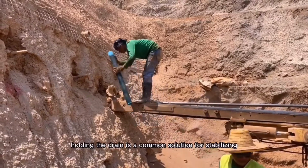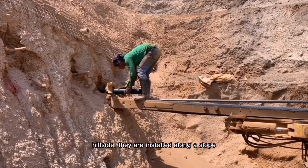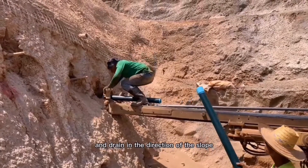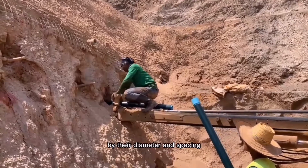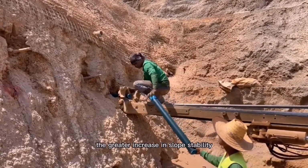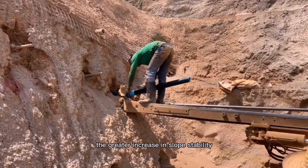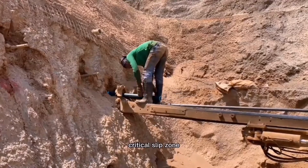Horizontal drains are a common solution for stabilizing hillsides. They are installed along a slope and drain in the direction of the slope. The effectiveness of drains is governed by their diameter and spacing. The larger the diameter or the lower the spacing, the greater the increase in slope stability, as well as their location in relation to a potential critical slip zone.